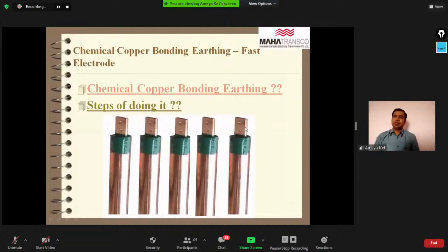So it is about the particular product demonstration by a particular company, and they are saying that other than this, there is no approved thing available in the market, but it's a false representation by the company. As per IS 3043, pipe earthing is accepted widely by that IS, that is Indian standard, and somewhere in IEEE standard 80, it is already mentioned that pipe type earthing and the plate type earthing are accepted, but not that as per that they are more effective compared to this type of chemical earthing specifically.